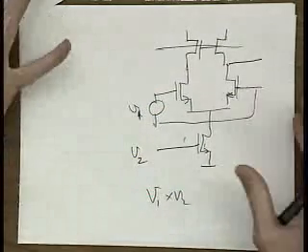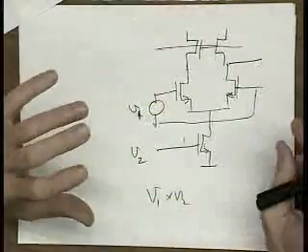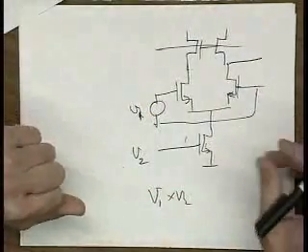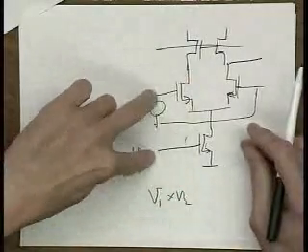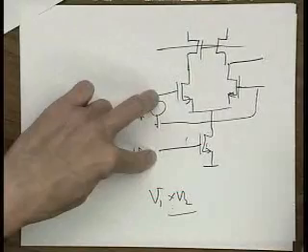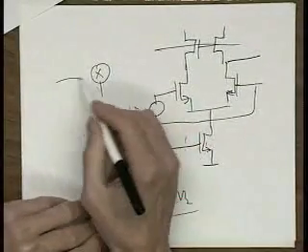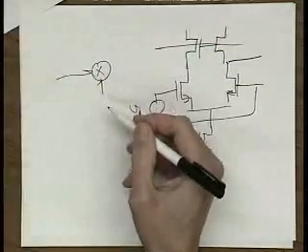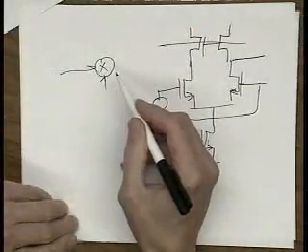So you've sort of seen this circuit before. And there are other cross-coupled ones that are actually even more efficient than this one. But this is the kind of idea of what you do. You put in circuits you've seen before, but you put two signals into it, and you end up with some sort of product on the output. So that's the mixer. I mentioned to you, mix down from high frequency to low frequencies. After you mix down to lower frequency, then you go into the baseband circuits.